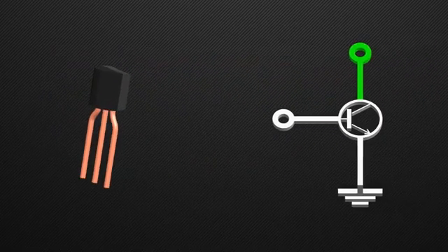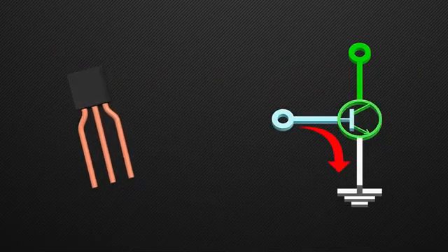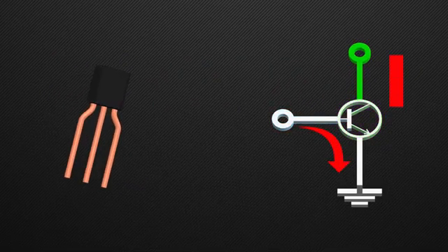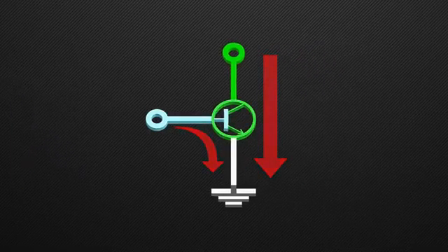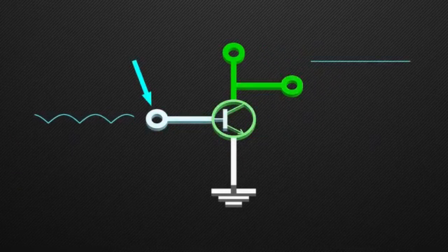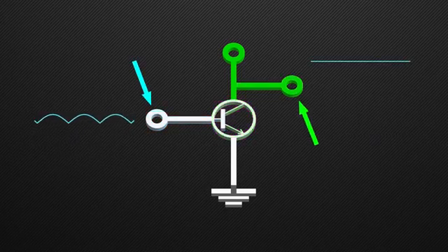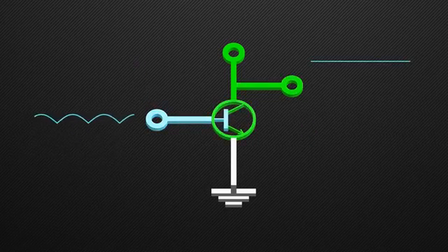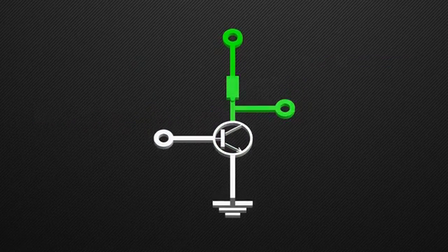You would know that the transistor can amplify the base current by its gain to the collector current. Hence, we will use the transistor to amplify the voltage applied at the base to a higher voltage at the collector. In this circuit, the output will always be VCC, as it is directly connected to the source. Thus we add a resistor between them.